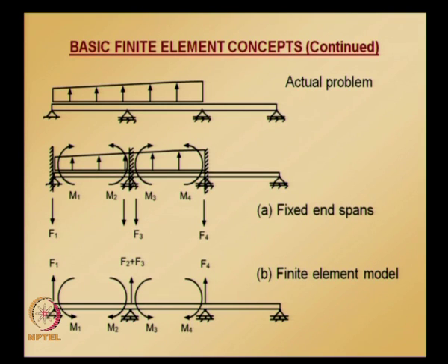Thus the final element forces and moments are obtained by superposition of the fixed end beam solution and the concentrated load finite element solution. Let us see how this superposition affects the computation of the element solution, and it affects only after calculating the nodal values obtained in the usual manner.